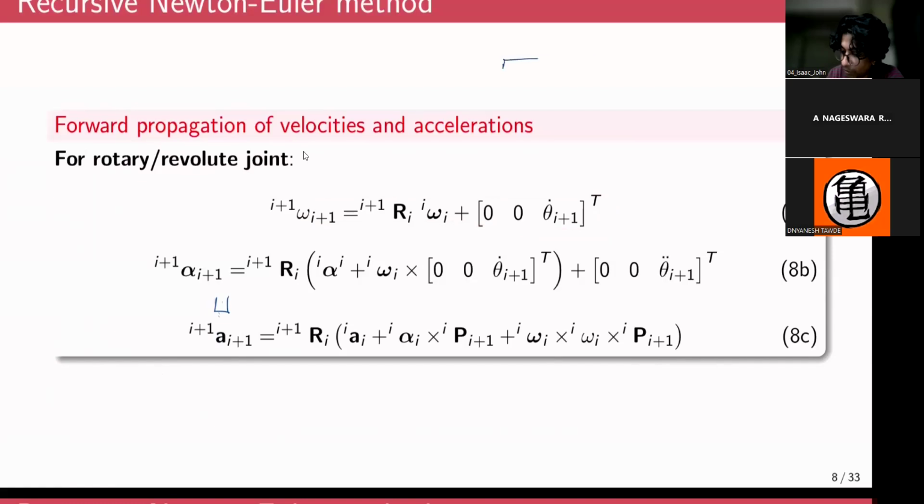For example, if you have a revolute joint, if you have a link, maybe I call this I, and we have another link over here, and I'll call this I plus 1. If I consider the joint to be vertically upward, the joint Z I plus 1 would be attached to link I, as per the DH convention.